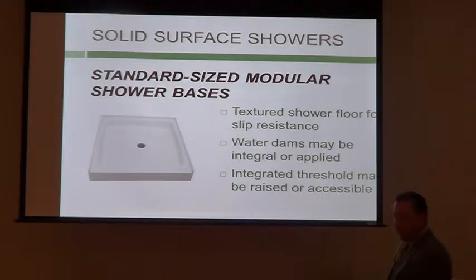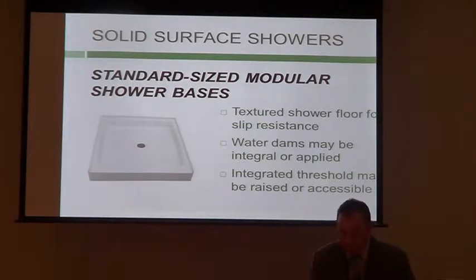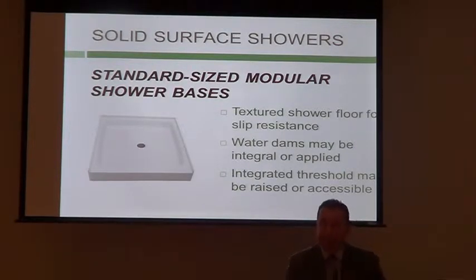What applied means in this case is we actually have a hybrid situation going on right here. It's impossible for you to see back there. The idea is this was all part of the mold, and the very top part of this water dam gets kind of narrow. If I had 2 stud walls here, that's the point of vulnerability, right? If I'm installing a shower base in the field and accidentally hit it against the wall, I could chip the top. So this has actually been reinforced by the manufacturer I work for, so it's stronger and thicker. It's a full 1/2 inch thick versus tapering to about 1/4 inch the way it comes out of the mold. So that would be an applied aspect to this integral design. This part was applied later in the plant.